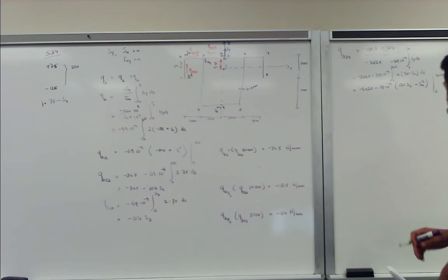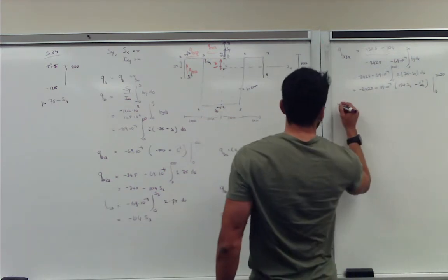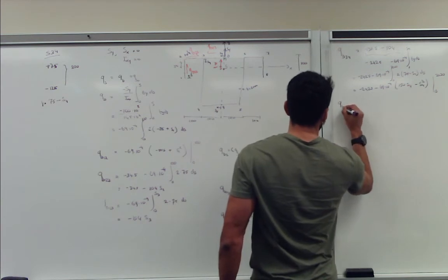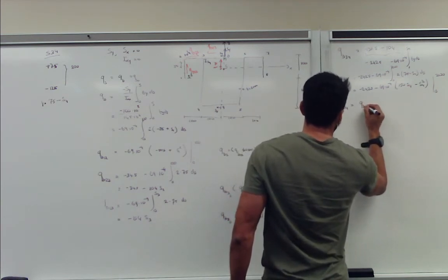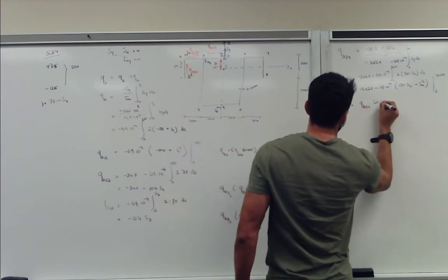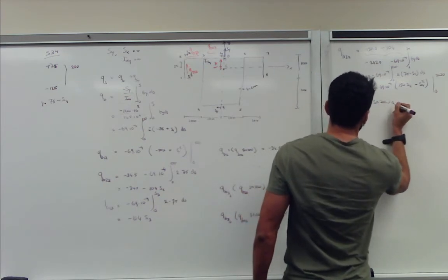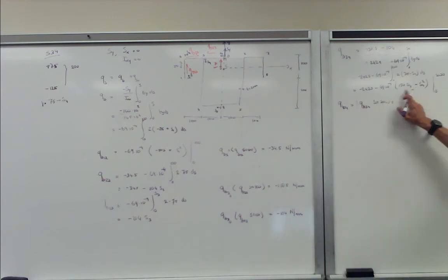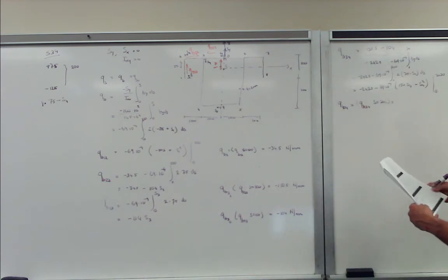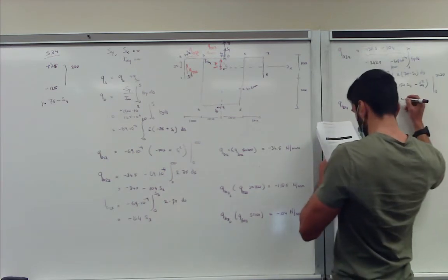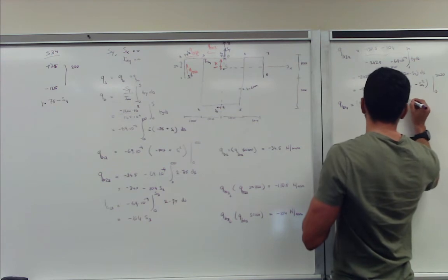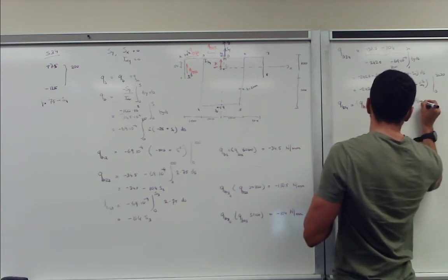Yeah, it's still readable. So at point 4, we have to evaluate Q4, or QB4, which is equal to QB34, and S is equal to 200. So we plug in 200 in this equation, and we can get our number out of it. And if we do this correctly, we get minus 172.5 Newton per millimeter.